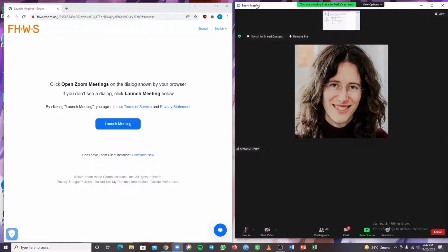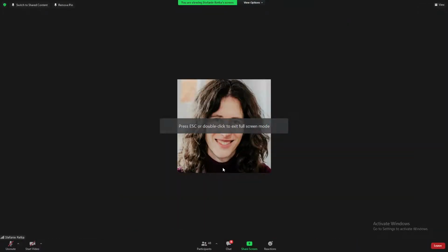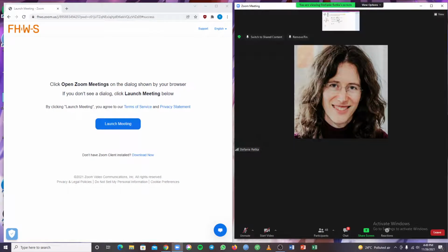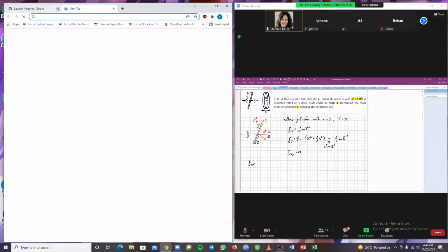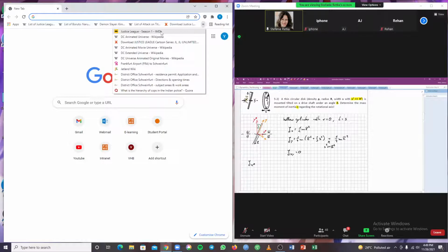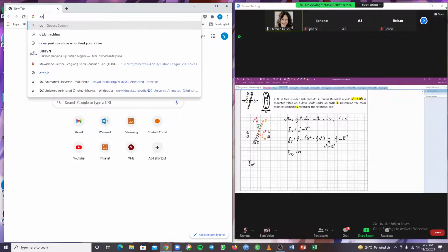Okay, then let's apply the equation for the mass moment of inertia with respect to the axis of rotation. Yes. Why is Jxy equal to 0? What is Jxy? Because x and y are the main axis of our system. We picked them as our main axis, so that simplified our computation. But what is Jxy? That's the centrifugal moment.